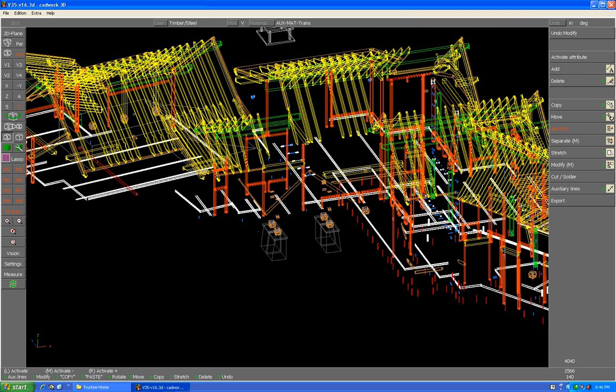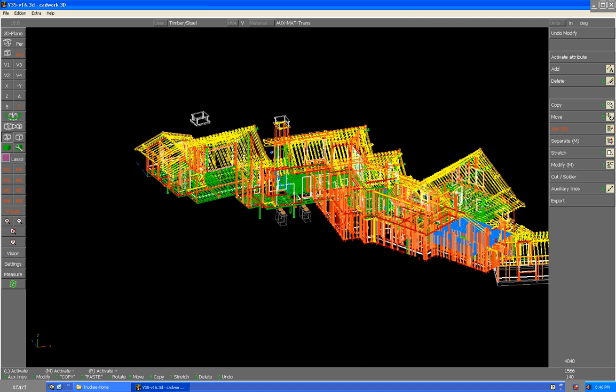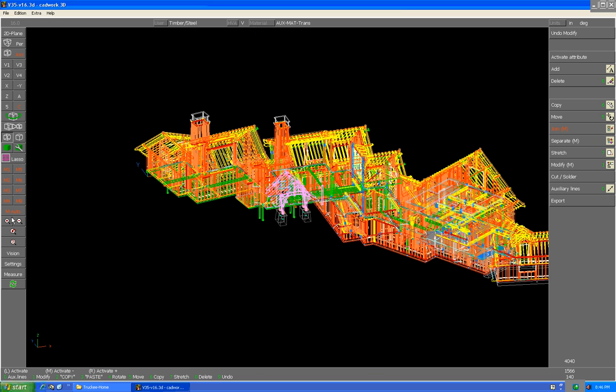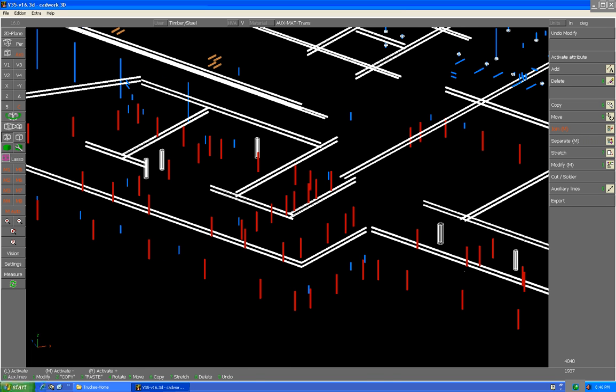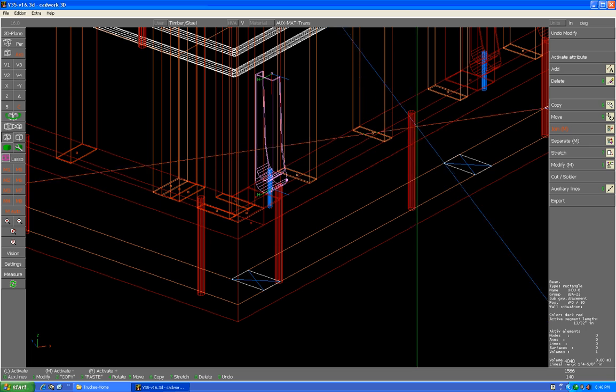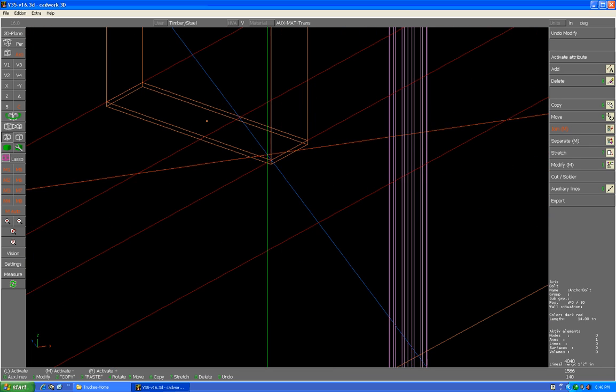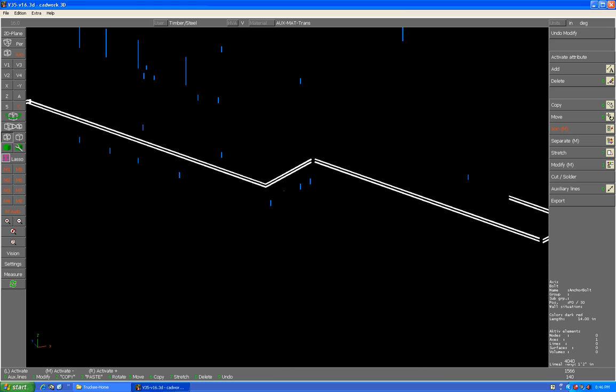Let's have a look at the walls. All the walls were panelized. We have in this house, for instance, 350 different wall panels. If I look a little bit closer here, you'll see all the hold downs are in there, all the anchor bolts. If I click here, it tells me this is, for instance, HDU8 in basement 22. These are anchor bolts, so all the plates will be pre-drilled. You'll see that this little extension here is a notch for our plates.